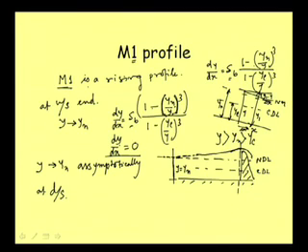Well, whether it is natural or artificial, the point is that this sort of structure or section we refer to as a control section. That means, at that section there is a definite relationship between the discharge and the depth. Well, we will be coming to that later when we discuss unsteady flow, then it will be more relevant to discuss that part.